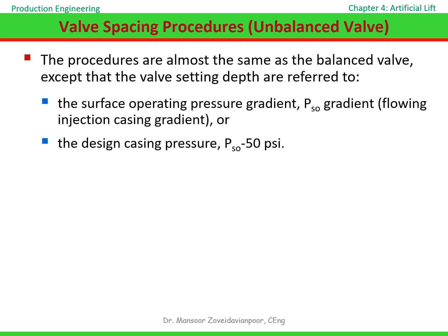The objective is still the same. Place the unloading valves so they open and close in the correct sequence and gradually transfer gas injection to the operating valve. So the methodology doesn't change much. Only the pressure reference changes.